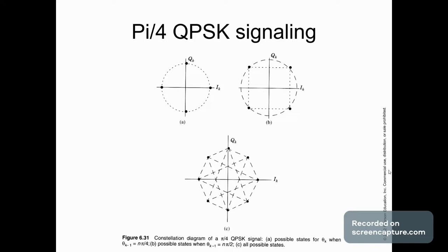So in other words, it's just a compromise of QPSK 90 and OQPSK. Sorry, QPSK 90 and OQPSK 90 degree. So pi by 4 makes it plus or minus 45 degree or plus or minus 135 degree. It is a non-coherent one, so no need for information from the receiver side. It can be used in multi-path fading. Bits are always 180 degree. So this is what the constellation diagram tells you, that any angle you take up, it results in 180 degree.